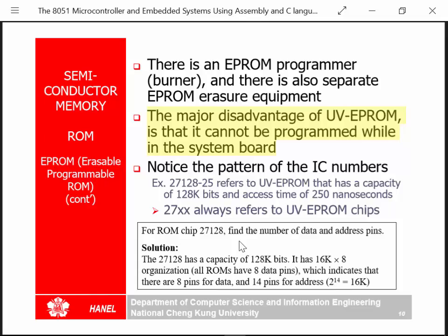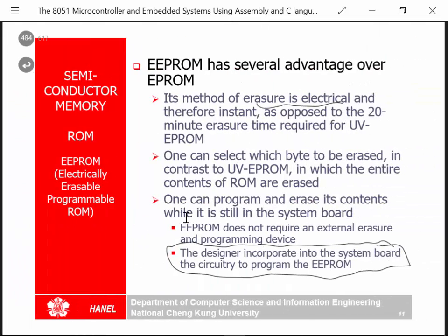So you could see the amount of time you spent erasing and reprogramming these devices. Not very friendly. And there is a pattern in the number: 27128 refers to 128K bits in EPROMs, all by 8, and an access time of 250 nanoseconds.